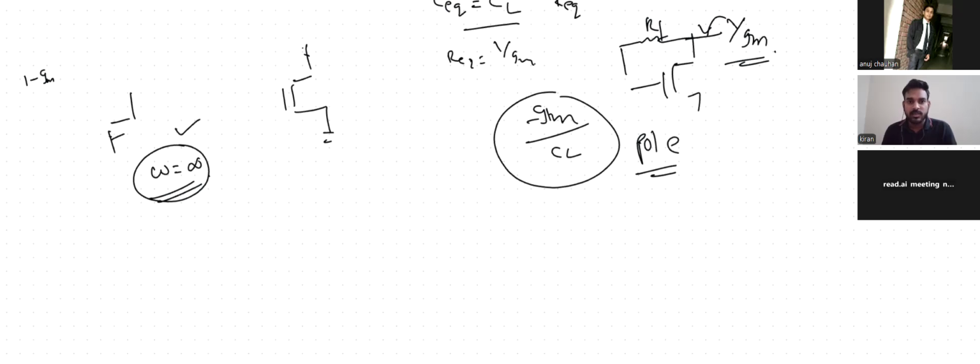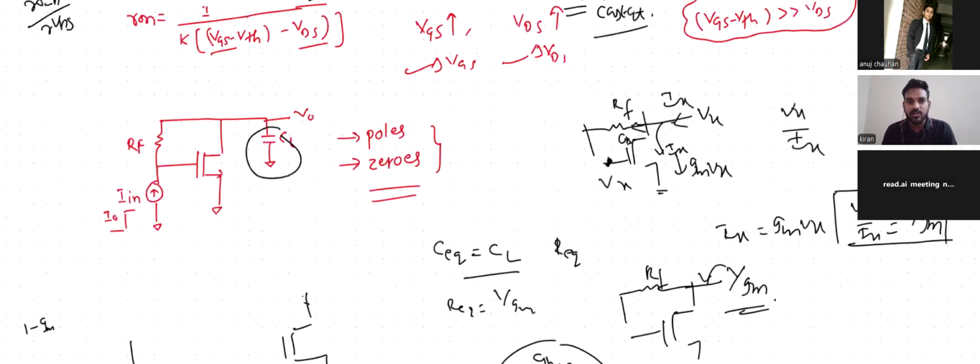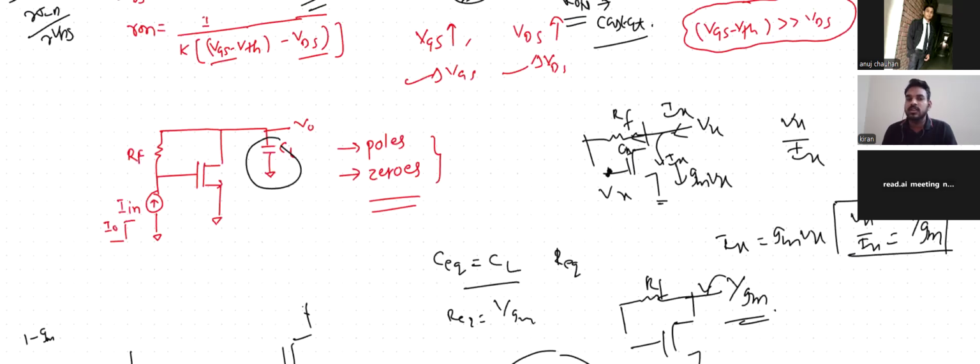I will see the basic principle from input to output. I will see whether multiple frequency paths exist or not. There will be a resistive element. Because of the load cap only, there will be no other cap here that we consider. Also, if any node from input to output can be made infinite impedance, there will be a disconnection between the input and output. Then the output will go to 0, which makes the transfer function 0. That we can consider as a zero.